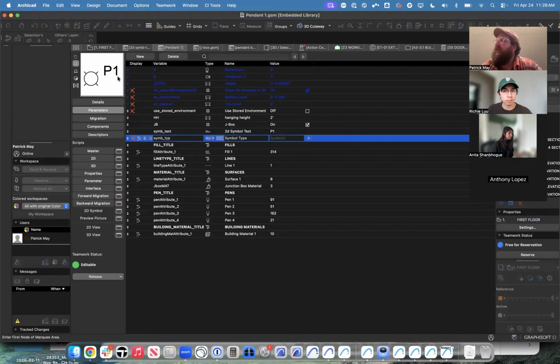Okay. There are ways you can technically do the trig and get it to put in a 3 in 12 ceiling and have it rotate to that angle. But I don't want to get into the weeds on that today, because that's me spending an hour and a half troubleshooting. I've done it before, and the reality is you can go to the roof settings, see what that is in degrees, and then punch that into the object. I know it's less convenient, but that's my recommendation for today. Okay, so I'm going to go ahead and save.